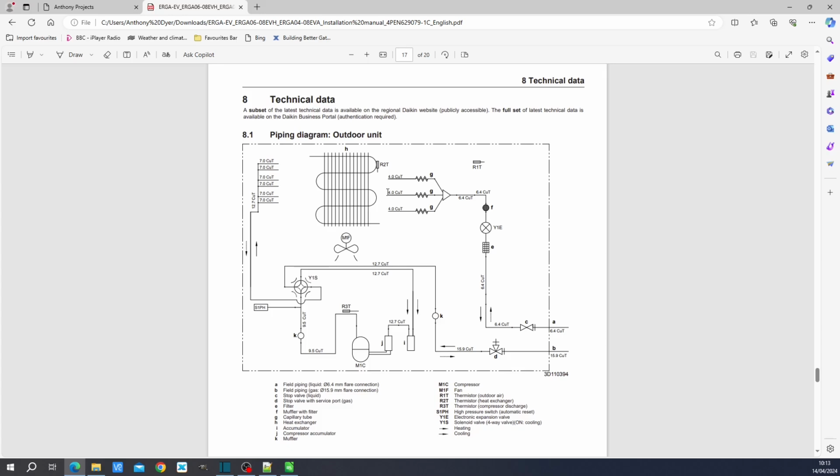What you have also seen is that the flow temperatures in the central heating were quite unstable at low temperatures. Sometimes they were oscillating up and down with a period of 3 minutes. What I think is going on here is that the flow in these capillary tubes is start-stop.